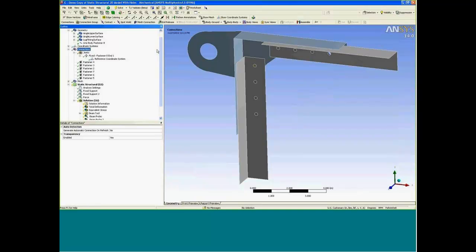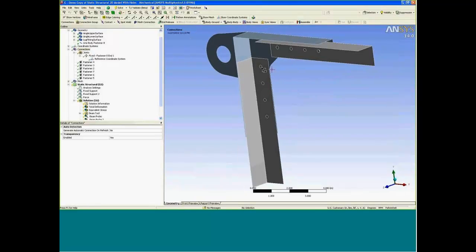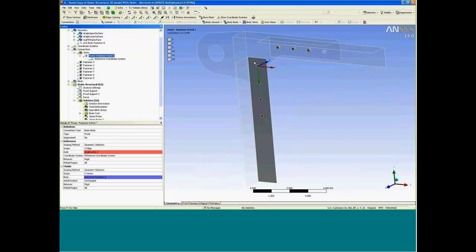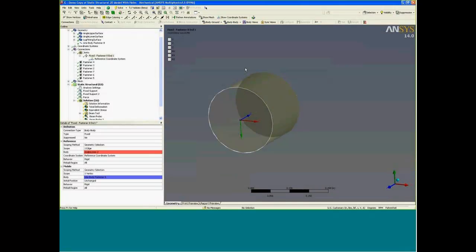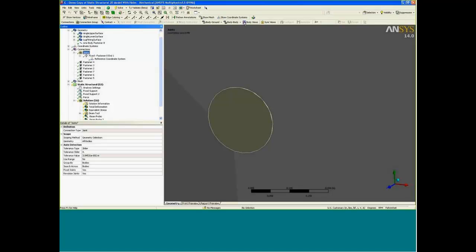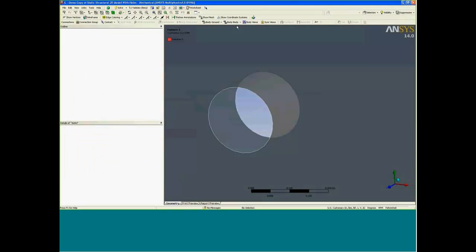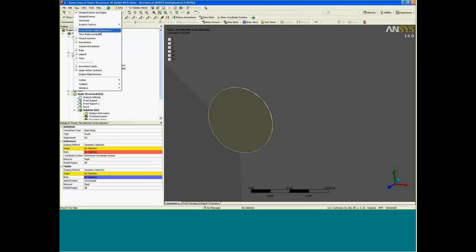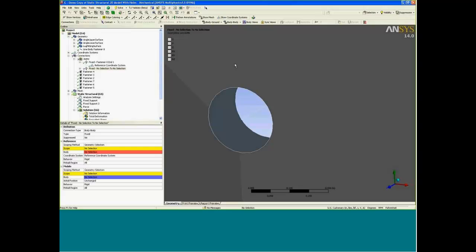First, let's take a look at our beam here and make sure we can connect our beam. With this existing beam, we're modeling that beam cross-section. We then have to connect the two ends of the beam to our various shell elements. And we can do that in our connection group, our joint folder, and we can go through the body-to-body and create a fixed joint. And that'll connect these two bodies. Let me turn off the cross-section solid so we can see that line body.